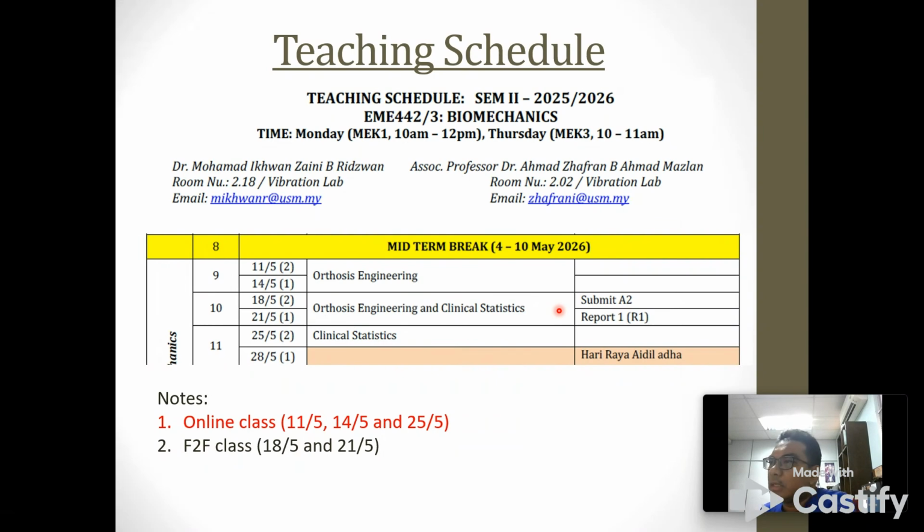You have been divided into groups, and you need to choose your own device, for example a grass trimmer, impact drill, grinder, or any tool in the lab that can generate vibration. From the data, you will do some calculations and classify the level of vibration based on the hand arm vibration chart.